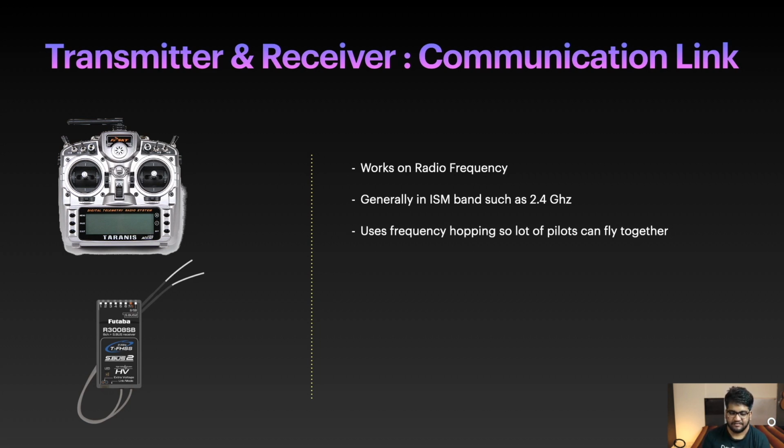Frequency hopping is built into the transmitter and receiver, and when you bind the receiver with the transmitter, they agree on the algorithm used for frequency hopping, and that allows a lot of pilots to fly together.